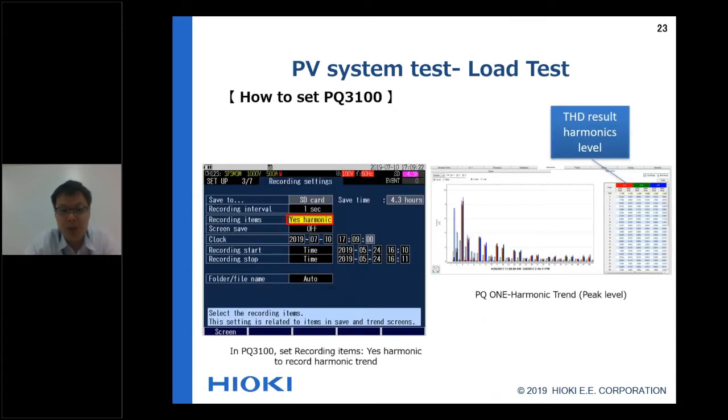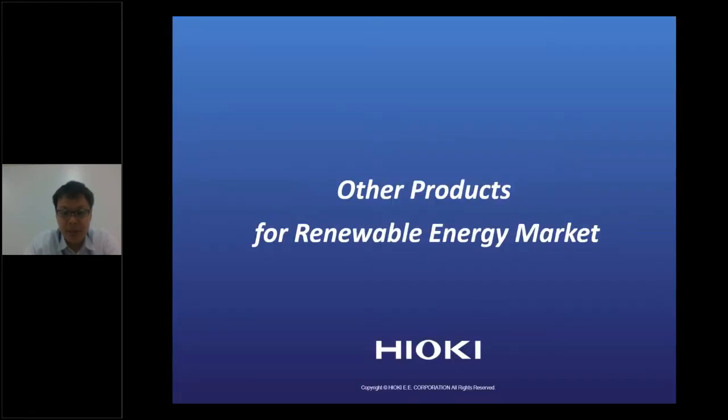Okay, so how to set the PQ? Please set the recording item to harmonics. Okay, like this. Only this one. And then you can see the harmonics value in PQ1, like this. Okay, so that's all about the PQA.